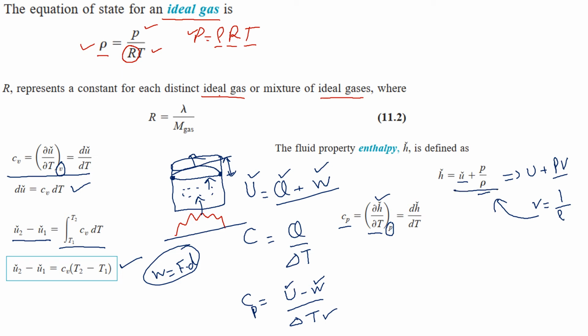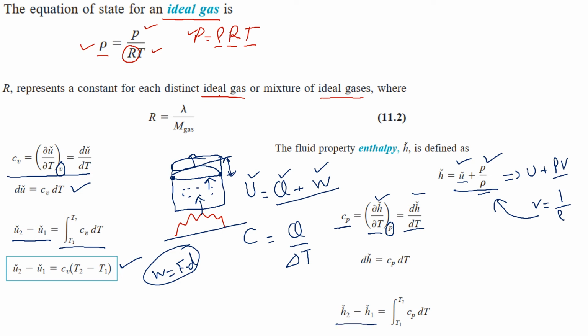Instead of enthalpy, that is the internal energy plus work done, it is also internal energy plus work done. So now we can see that Cp is equal to change in enthalpy over change in temperature. So now we can write this equation like this and simplify it a bit more to find the change in enthalpy for our gas. That can be any gas at any 2 points. These are state functions. That's why we are talking about 2 points, the change in enthalpy at point 1 and point 2, and that is delta H, and that delta H will be equal to this function.